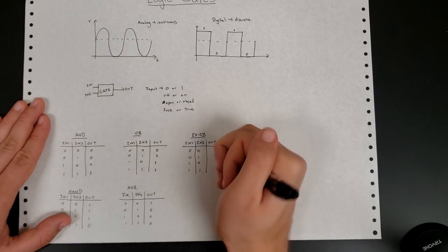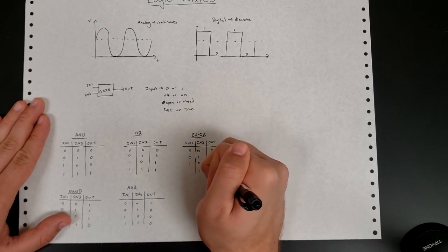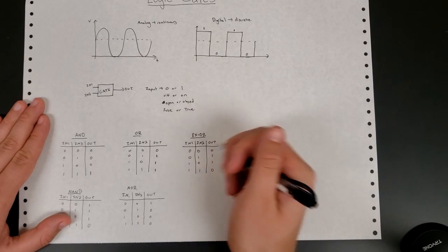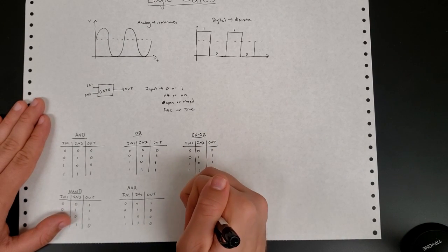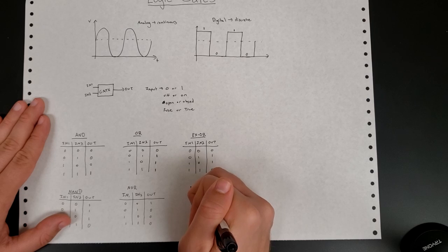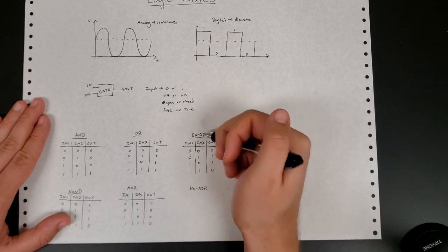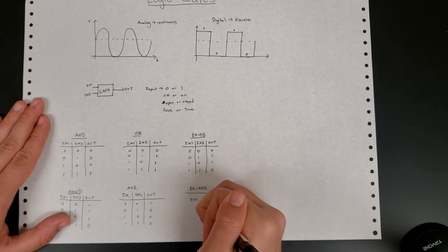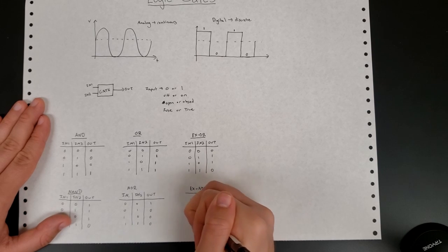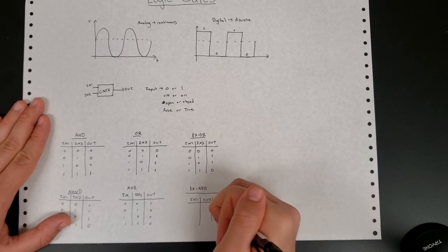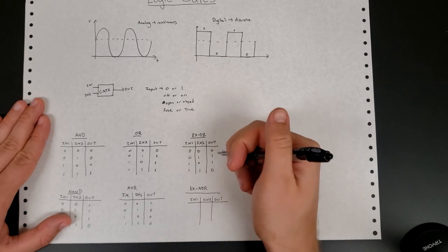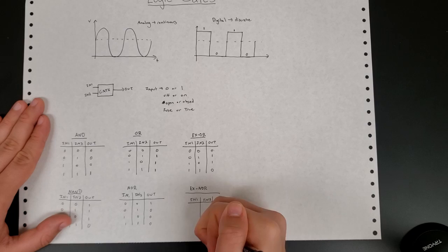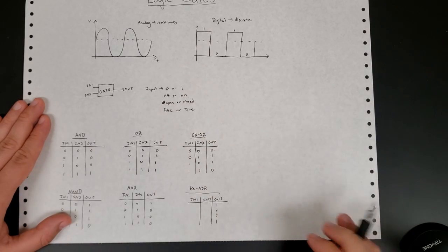So our output would be the same as our OR, like I was saying, except for this last one is 0. Okay, now I don't want to continue to just rewrite all of these, but for the exclusive NOR, which is the negation or the inverse of our exclusive OR, we can say N1, N2. I don't want to rewrite these inputs, so I'm just going to only write the output. It's going to be the opposite of this, so it's going to be 1, 0, 0, 1, right? Where the inputs are the same as all the other ones that we've been doing.